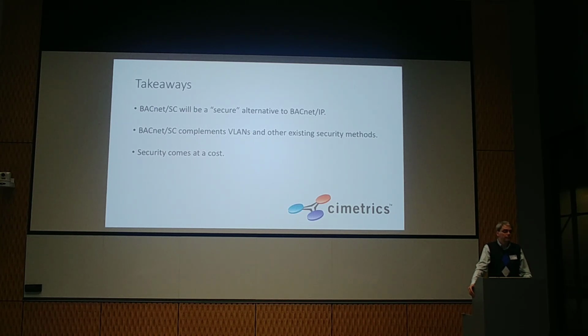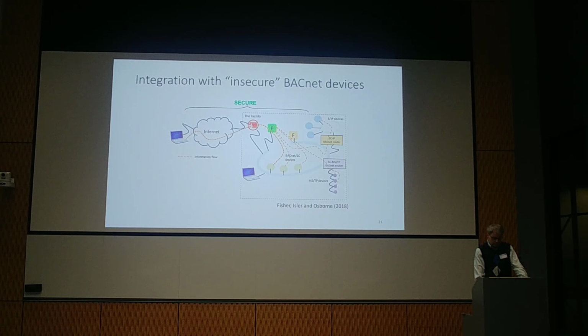On the last topology slide you had up there, forgive me if this is a little nuts and bolts simple, but if I were to take my operator laptop and plug in, say, on that unsecure BACnet IP ring you've got, would I still be able to see the entire network, including the SC devices? Is that the nature of having an unsecure leg? Yes, that's true. BACnet SC only secures the SC part of the network.